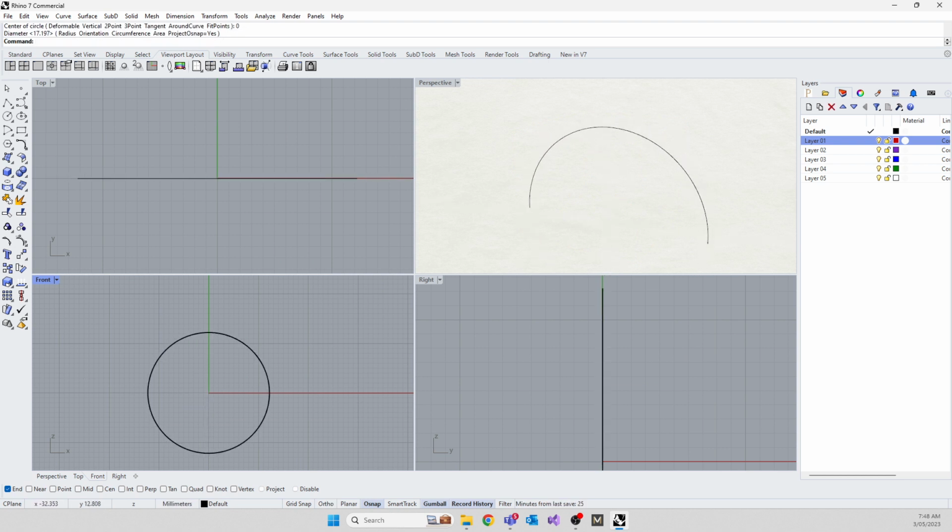And I'm going to make a line. I'm going to turn on that one, and I'm going to turn on end. Okay, we're good there, and I'm going to turn on quad. All right. So what those snaps are doing for you on the bottom over here is when you're drawing, it wants to help you. It's saying, can I help you find this item? Can I help you find the end of an item? Can I help you find the mid of an item? Can I help you find the quad of an item? So I'll do these three today.